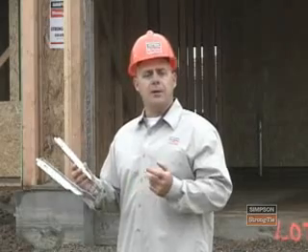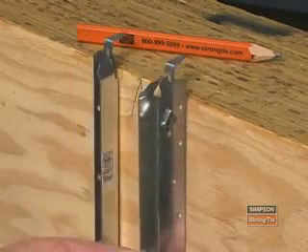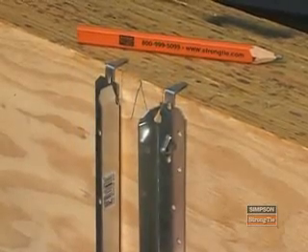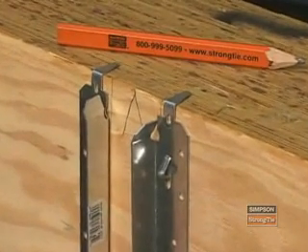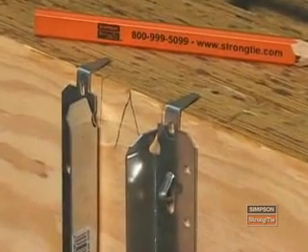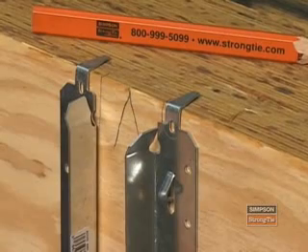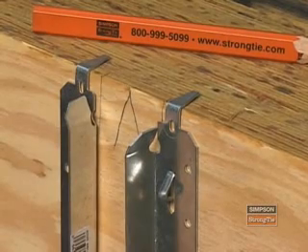To install an IUS series hanger, you follow many of the installation procedures for the face mount hanger and drive 10D common nails through the header flanges into the header. The quantity of nails required varies by hanger size. The installation is faster than that for a face mount hanger because the top set tabs hold the hanger on the header face at the right height and eliminate the need to measure and mark the hanger position.